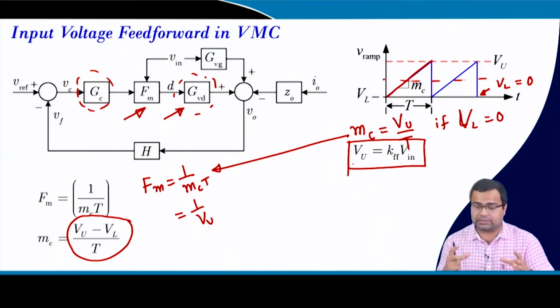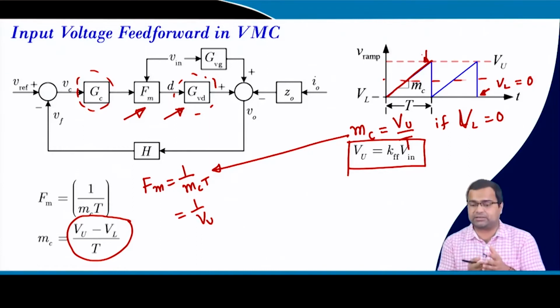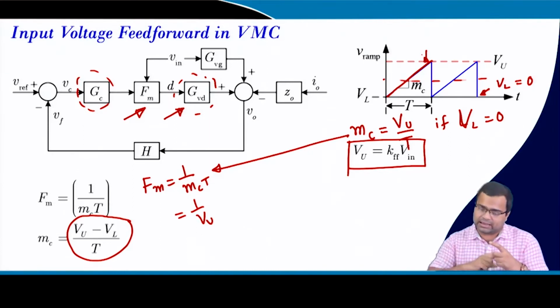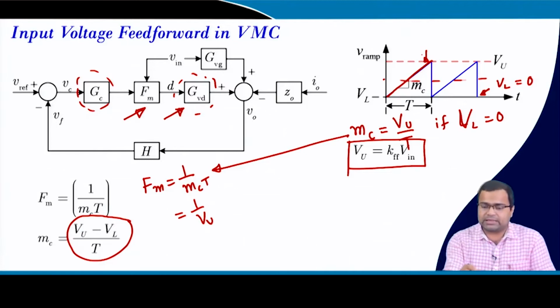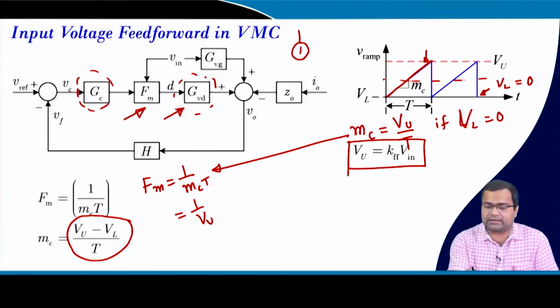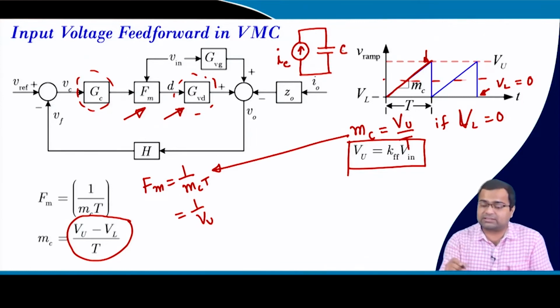And we also discussed in integrated circuits how I can do that, because generally these waveforms are generated by using a constant current charging a capacitor. So, the output of the capacitor will look like a sawtooth waveform. Now, the slope of this sawtooth waveform is decided by two factors: the magnitude of this constant current and the capacitor.